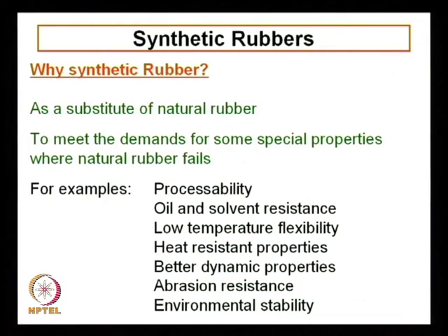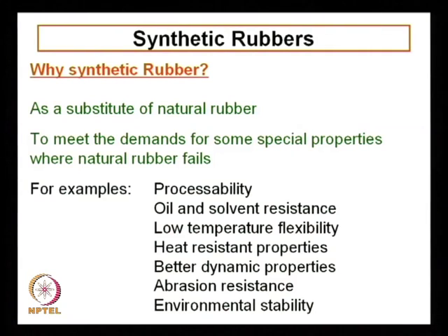So, this is one property, and there are certain applications for high temperature sealing in oil environment. So, the environment is high temperature as well as in contact with some petroleum oil, there you have to use special purpose rubbers like say silicone rubber or fluoroelastomers will be suitable there. Okay. So, this way we go for special purpose rubbers depending on the properties we need.